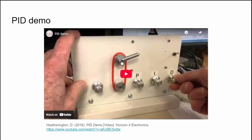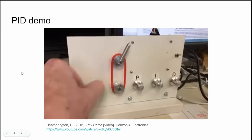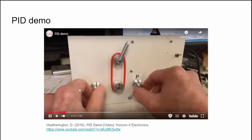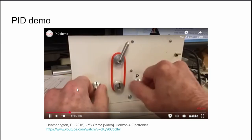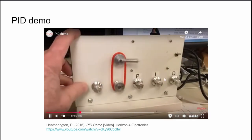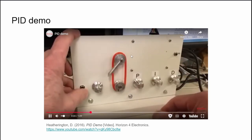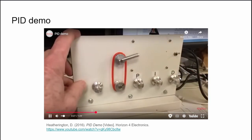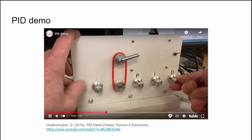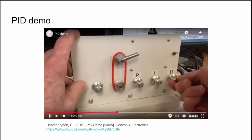So here is an example of PID. The demo moves a motor to go either to the left or to the target value set by the leftmost knob. This is set by a switch on the very left here. The tuning parameters for the proportional, integral, and derivative can be set by turning these knobs on the right. When the proportional tuning is increased, it'll move faster, but it'll shake more. When the derivative tuning is increased, it'll run slower, but it will prevent overshoot. However, it may undershoot the target value because not enough power would be given to the motor.